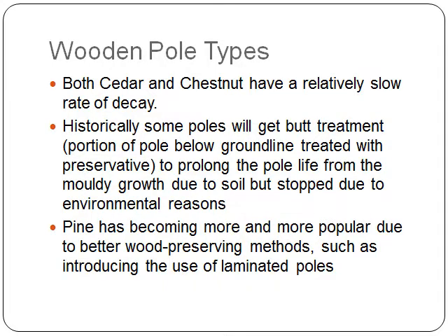Historically, some poles would get butt treatment, which is treating the portion of the pole that's below the ground line with preservative in order to prolong the pole life from the moldy growth due to soil. However, after using it for a short while, it was stopped due to environmental reasons.